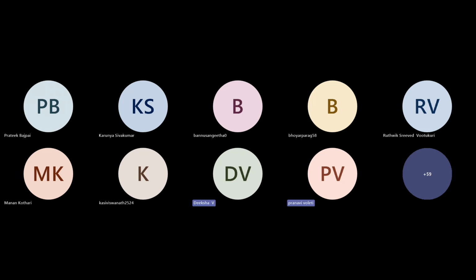So components could be moved, but bodies can't be moved. So when we make a body into component, we can move them and join them together. While using the assemble option, you can't use assemble by having bodies. So you have to basically convert them into components, and then if you assemble and put your constraints, you can make a body move, something like that.